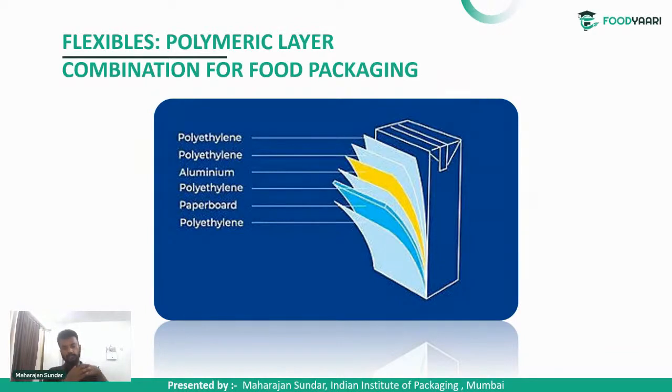It will be used in a sheet form, and then the aluminum, again in the inner part, can't directly attach with polyethylene, so in a melt form the polyethylene is introduced, and a polyethylene sheet is again introduced over it so that a layer is formed, and various mechanical steps are done to form a tetra pack until it is filled. And the polyethylene layer is the inner layer which contacts with the food.